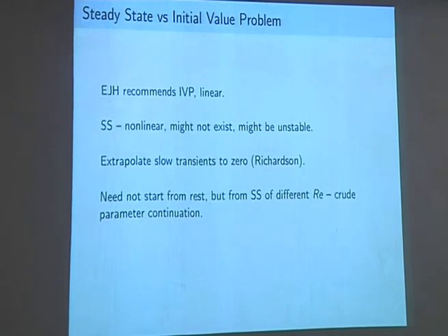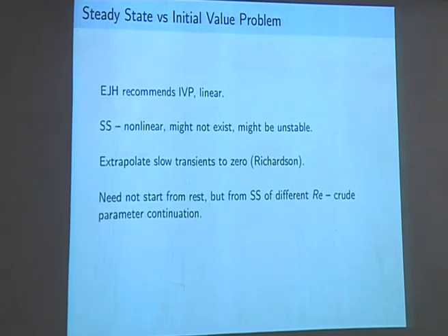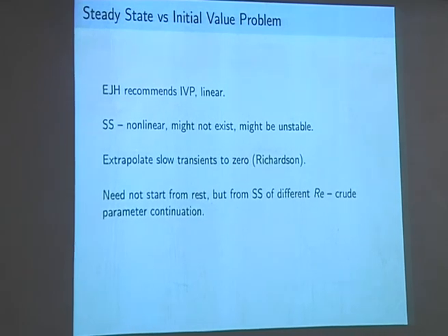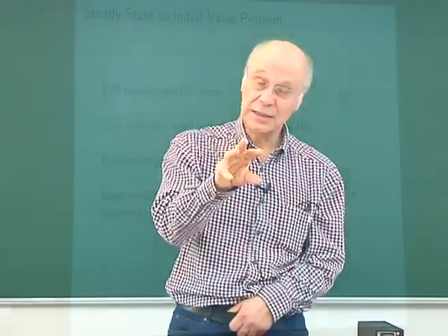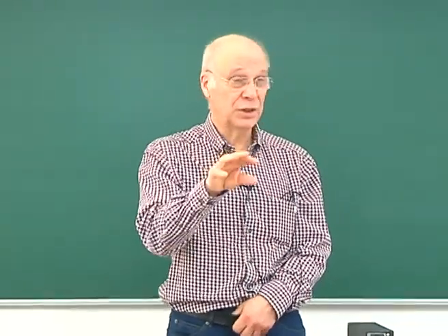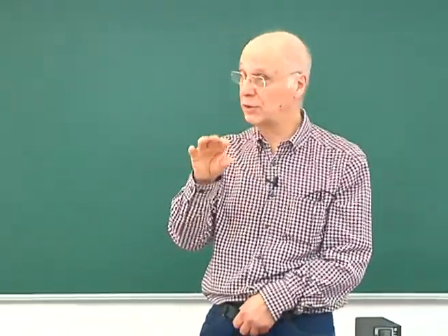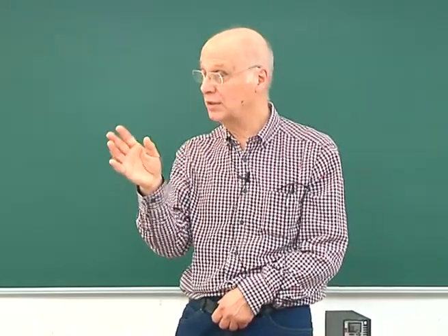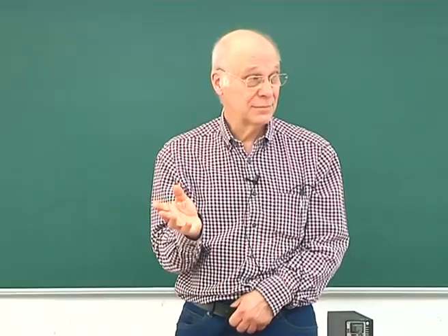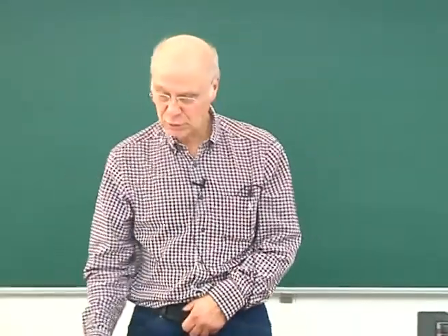And you don't actually have to start from rest. Sometimes we're interested in, say, the force on this plate as you vary the Reynolds number. Well, if you get a solution at Reynolds number 10, you could then use that steady solution at Reynolds number 10 as the initial condition for Reynolds number 20. And that might be quicker than starting from rest. So there are little tricks around. There are always little tricks.